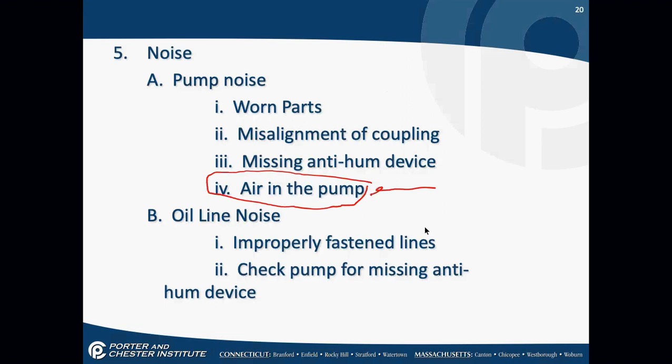In the middle of the night, to some homeowners, that sounds like someone's in their basement. There's a noise that they can't identify. It wakes them up. And by the time they wake up fully, there's no way to hear that noise again. So it can actually drive people nuts. But again, be careful about air. Every single time I've seen a service technician ignore air, there's usually a big oil spill that has to be cleaned up, because where there's air, there's a leak.